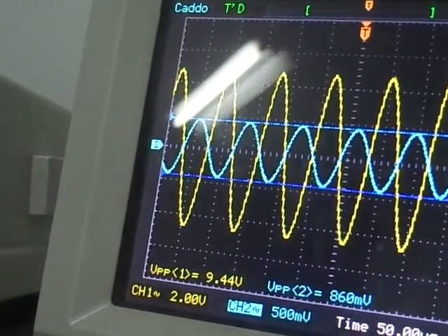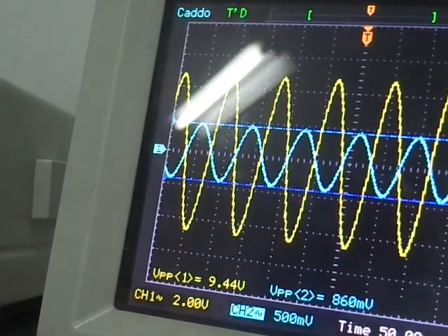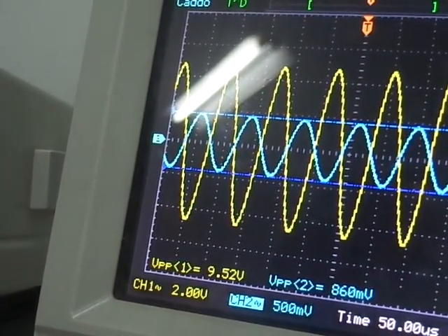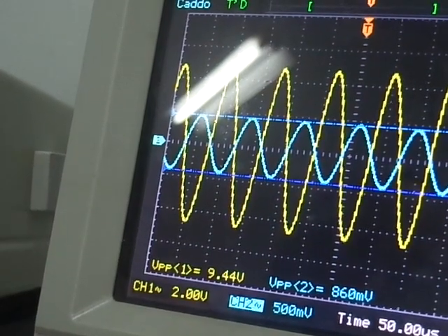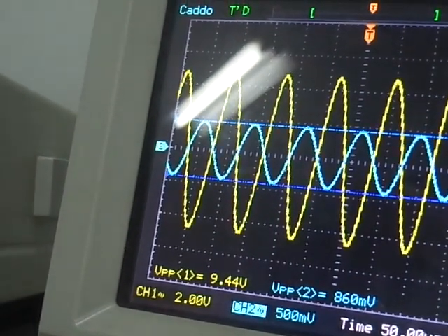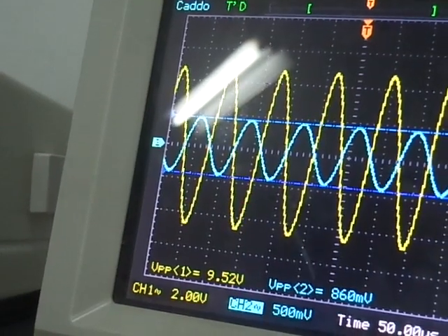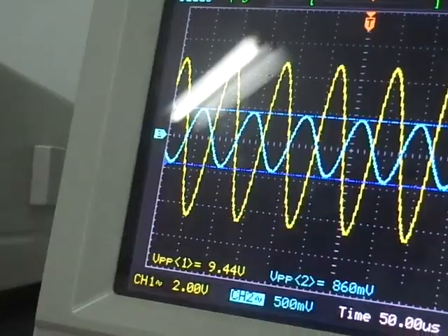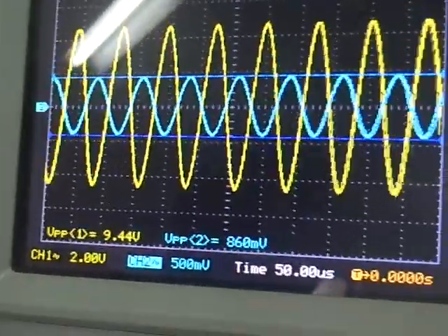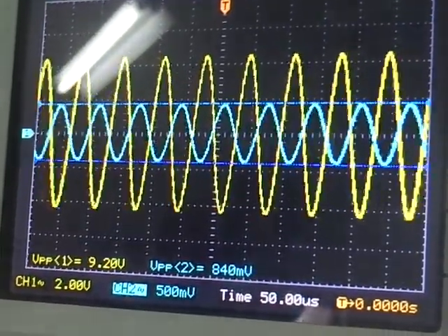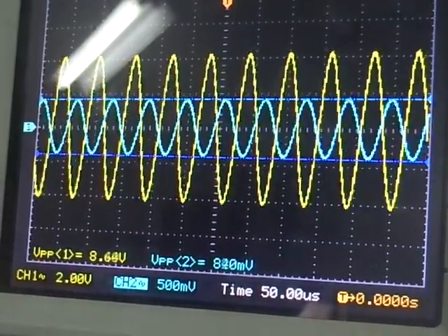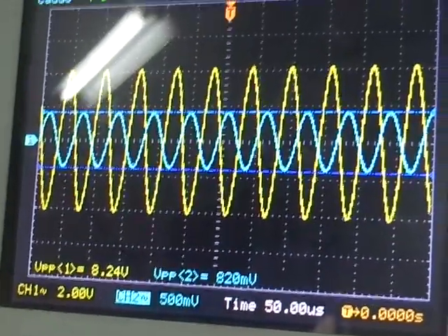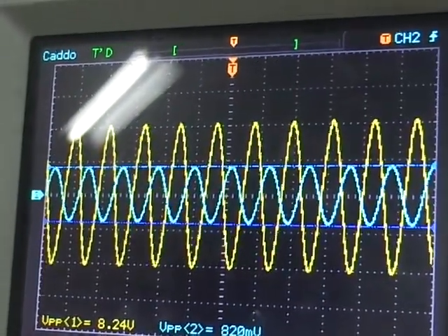At around 12 kHz we are getting the maximum value, and after that the output starts decreasing. So the design frequency for the differentiator, FB, we selected as 16 kHz, and practically at 12 kHz we are getting an output voltage of 9.52, which is then decreasing. That means FB we are getting as 12 kHz. After that, the output voltage goes on decreasing. Whatever graph we considered, initially the output voltage increases and then decreases, and that is also obtained here.